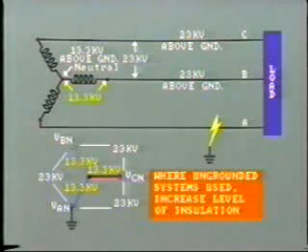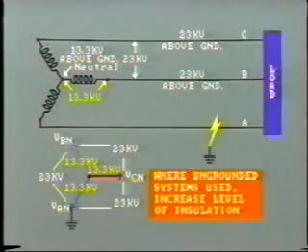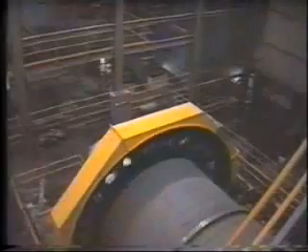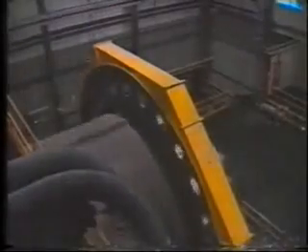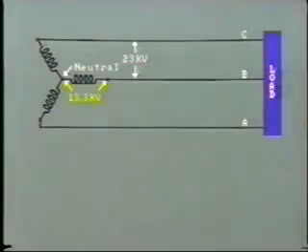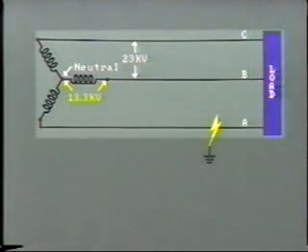This will greatly stress and possibly damage the line and equipment insulation. In fact, where ungrounded systems are used, it is normal to increase the level of insulation to withstand at least line-to-line voltage. But why would anybody want to run their system ungrounded? Well, one reason could be to ensure continuity of supply. For example, an industrial installation which must have minimum outage. In this case, if a ground does occur on one part of the system, no tripping will occur and power supply will continue. The three phases will continue to feed the load and retain the normal phase relationships.